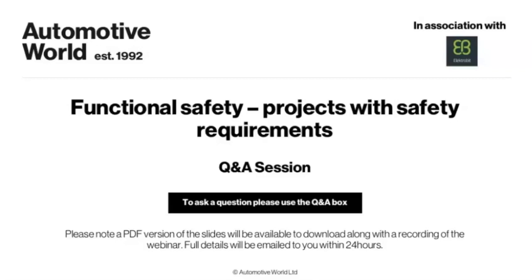Somebody's pointed out that on slide 9 you've listed FSR and normal functional requirements separately, and they've asked whether this means that safety requirements are not part of functional requirements. No, actually, functional safety requirements and functional requirements coexist. They are normal requirements and need to follow the same rules, but they have a different origin. They're derived out of the safety goal.